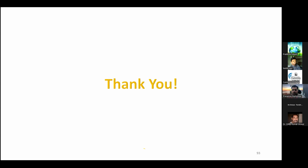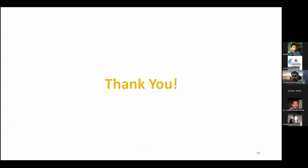One question from a participant is whether two dissimilar materials can be welded with CMT. Yes, it can be welded. I have this paper, and the participant can refer to it. Thank you for sharing, sir. In VNIT itself, we have performed this welding. In VNIT, we welded 316L and 430.